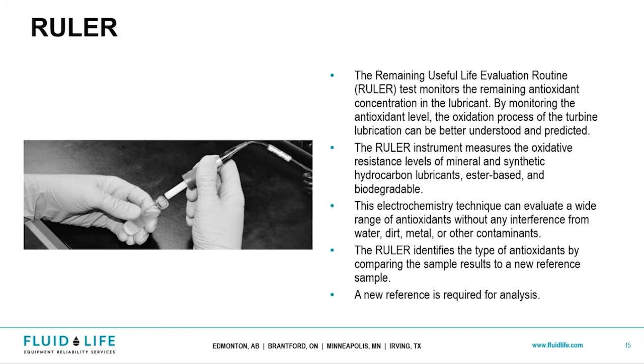And when you're looking at conventional tests like your kinematic viscosity, your total acid number, your FTIR data, your ICP, all that stuff, those are going to measure the extent of that degradation after it's already occurred. So this is just something that gets ahead of that. And when you're looking at different types of greases, of course they've got a whole bunch of different additive formulations. Some of them are meant to drop out, of course. This is just looking at that before you even start seeing that. So this is where you get really fancy with some of the testing.